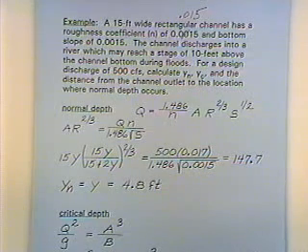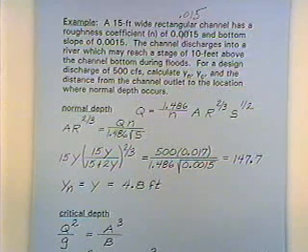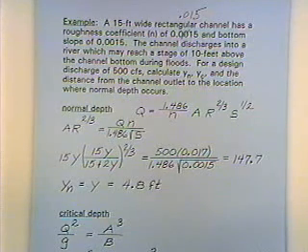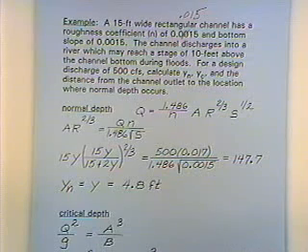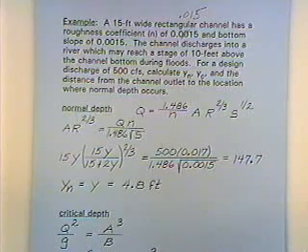So one question right offhand, are we going to have a hydraulic jump? Will there just be uniform flow until we get almost to the river and have a hydraulic jump? Or will there be a smooth transition over a long distance, half a mile, 2 miles? A very smooth transition from the normal depth to the 10-foot depth in the river. To answer these questions, we need to know what the normal depth is and what the critical depth is. And so we'll just compute them.